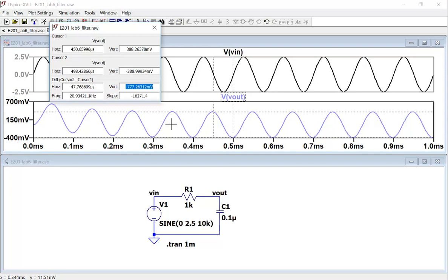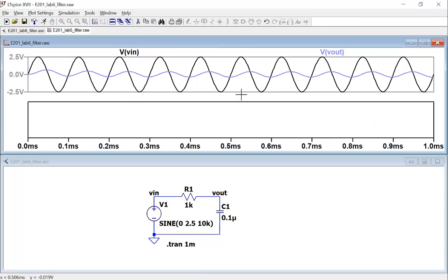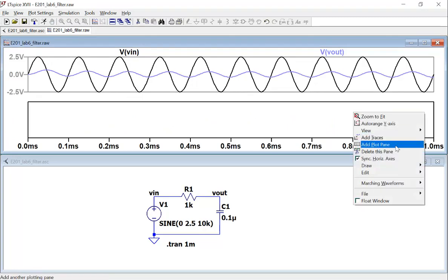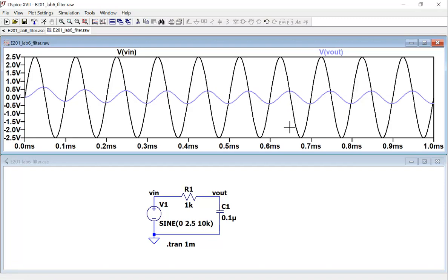The first task you have to do, okay? That's the first one you have to do. And what about the second one? It's going to be the phase shift. How to get the phase shift over here? Still, you have to do all the data points, all the frequency points, and plug in all the time differences you measured on an oscilloscope and report it to the Excel sheet before you plot it.